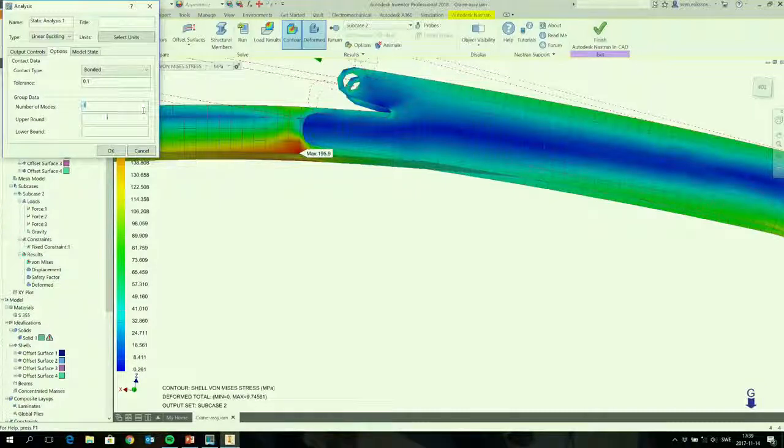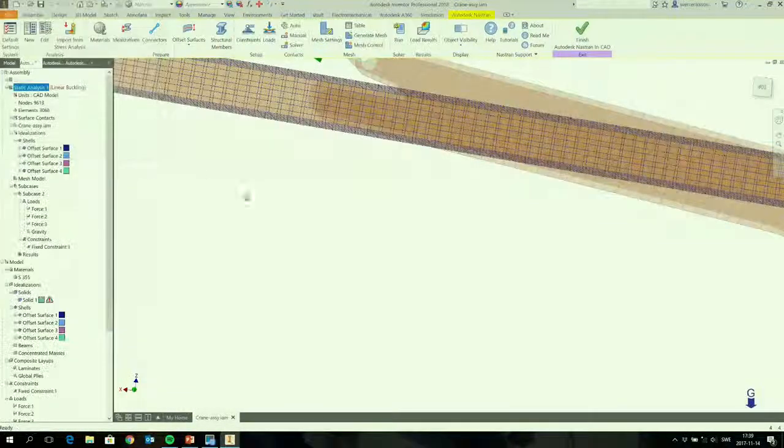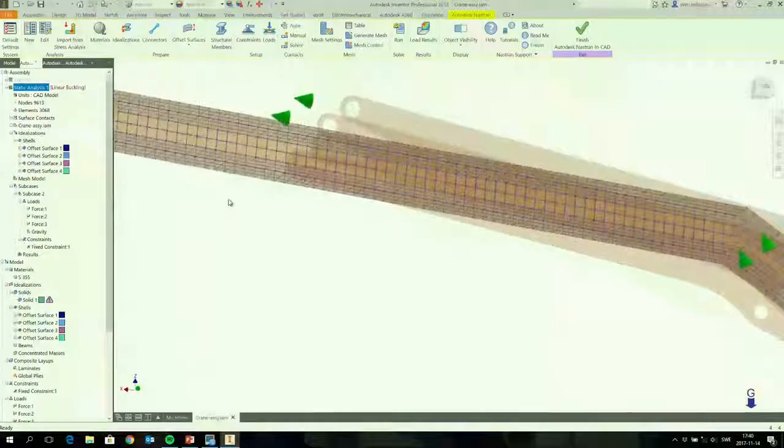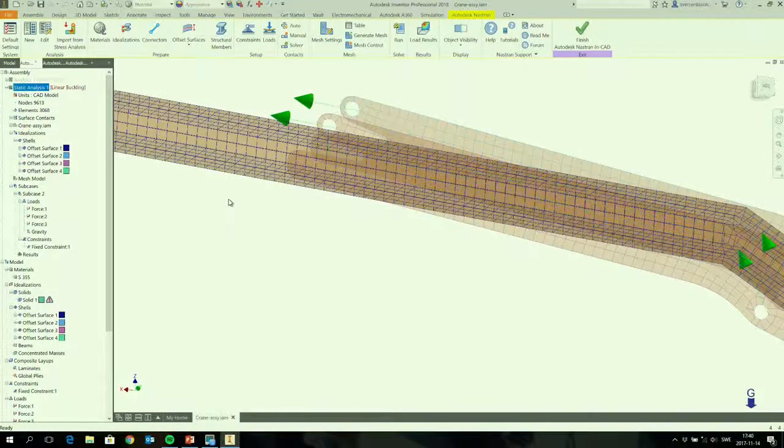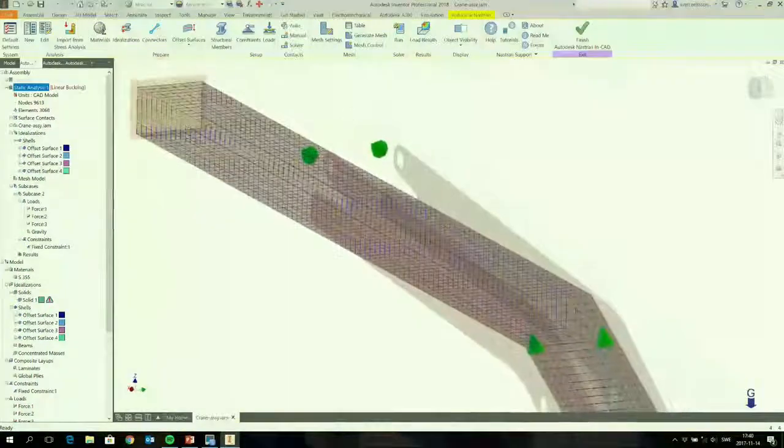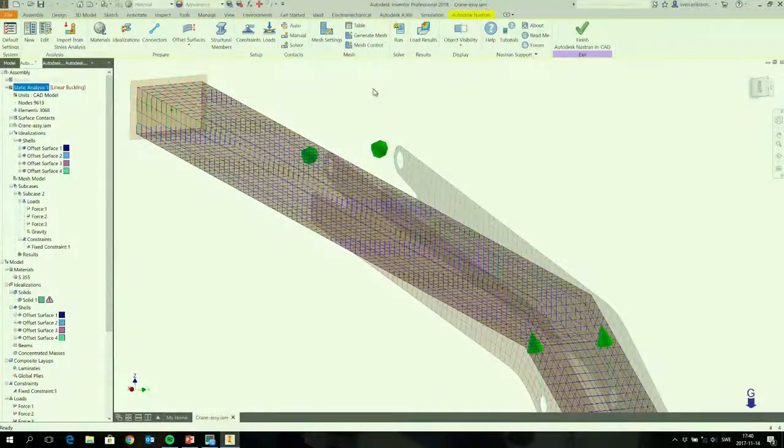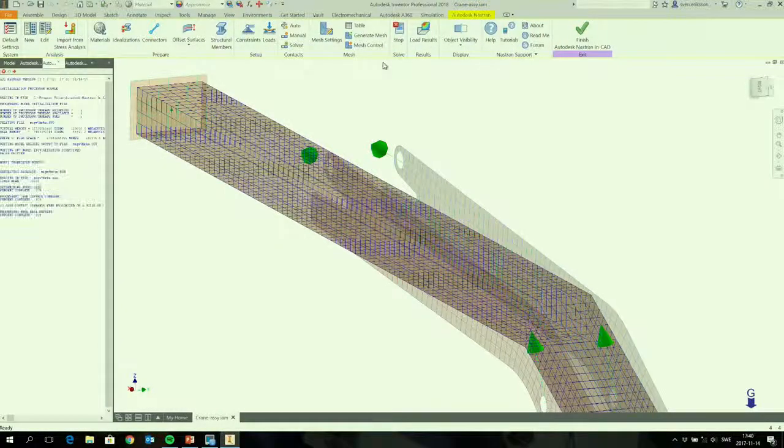In this case, I say I want to see 4 just as a figure. And I click OK. And I can choose which representation level I want to be in. If I have done a special FEA level, I can use that one. So this is what's done. We have 4 modes that we are going to look at, and we click run again.